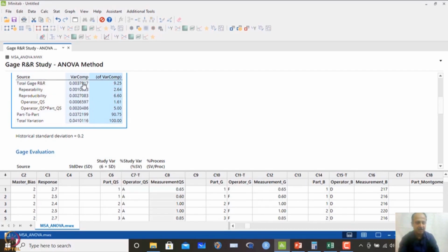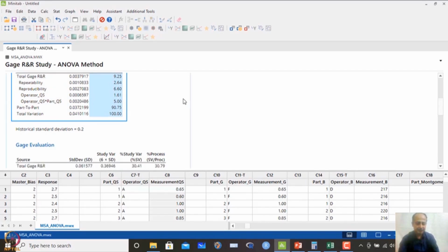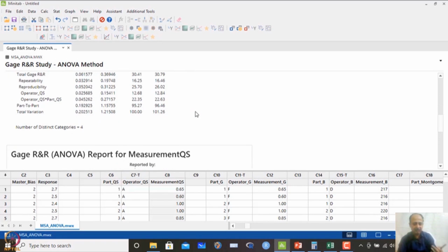Maybe this 10% that we are getting, more than 9% will reduce over here. So, we have to take actions where it is necessary. Reproducibility is a problem over here, we can reduce repeatability. So, that will reduce the overall 30% criteria that we are having. What action to take, whether to send to metrology or it is operator variation, we have to take action, because operator to operator variation is also contributing to the overall variations of the measurements that you are getting.